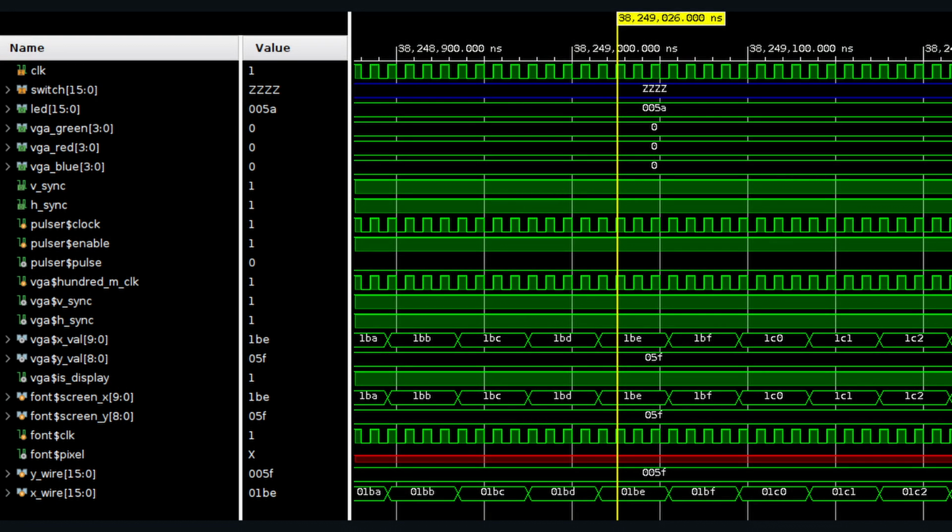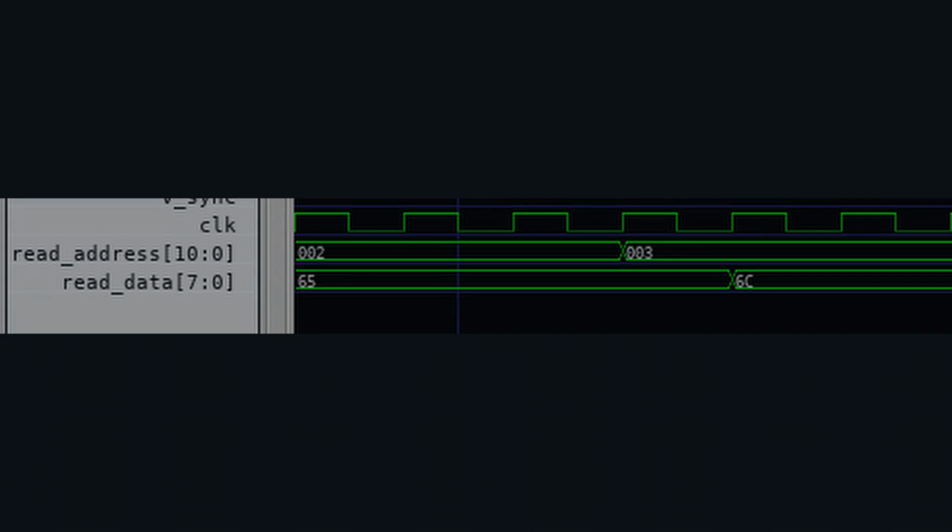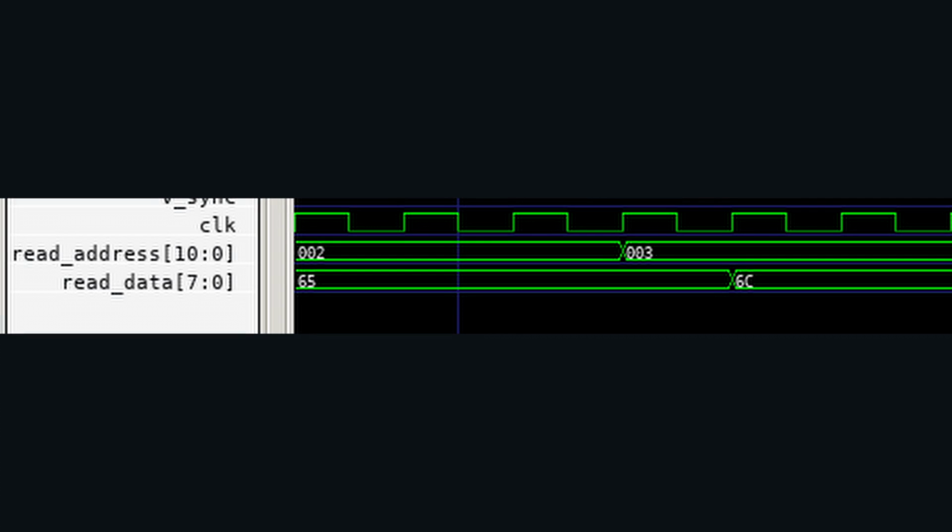When designing a circuit and hardware, it's a lot of worrying about which cycle everything is happening on. Remember the heartbeat from earlier? Yeah, so in a simple example, if I want to read from a RAM, then I'll set the read address, and now the data won't show up until one cycle later. Then let's say I do a multiplication and store the value.